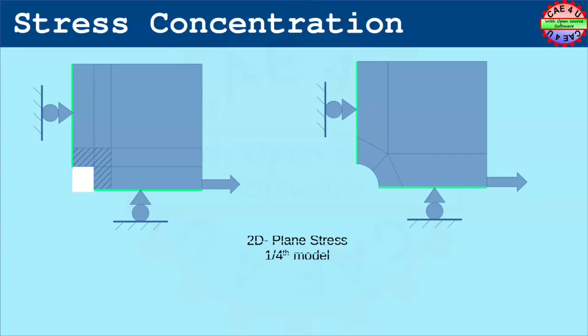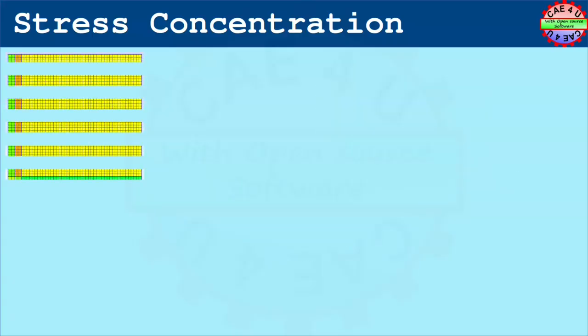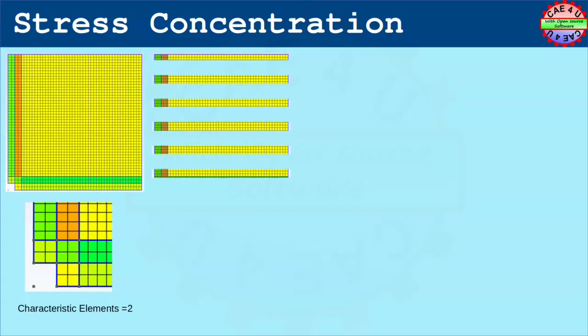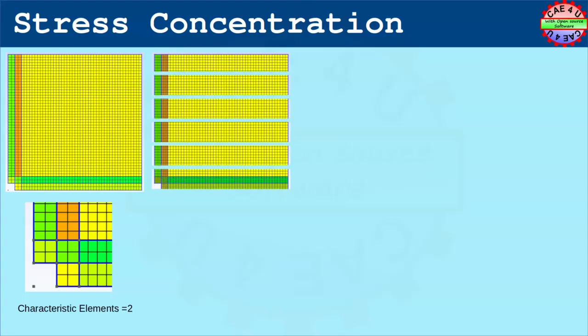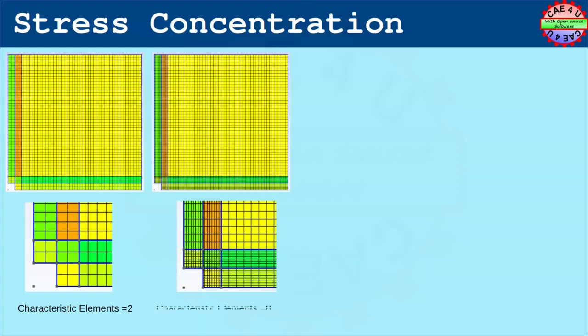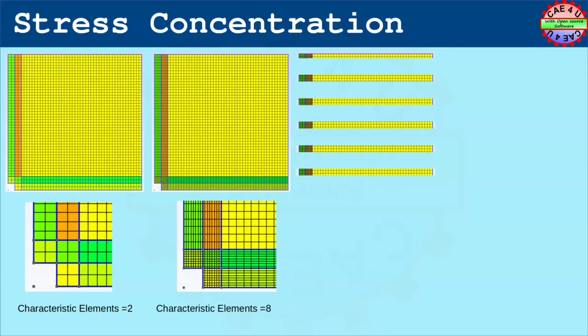We will use the same boundary conditions and the loading conditions for both the cases so that it can be compared easily. It is important to understand the mesh convergence, particularly near the cutout. So we have chosen a characteristic number of elements of 2, 8, 16 and 32 in the buffer zone. As we see the mesh, it could be easily observed that, in the far field, uniform stress is expected, so the number of elements can still be lesser. However, in order to avoid any stress jumps, we will still maintain reasonable fine mesh.